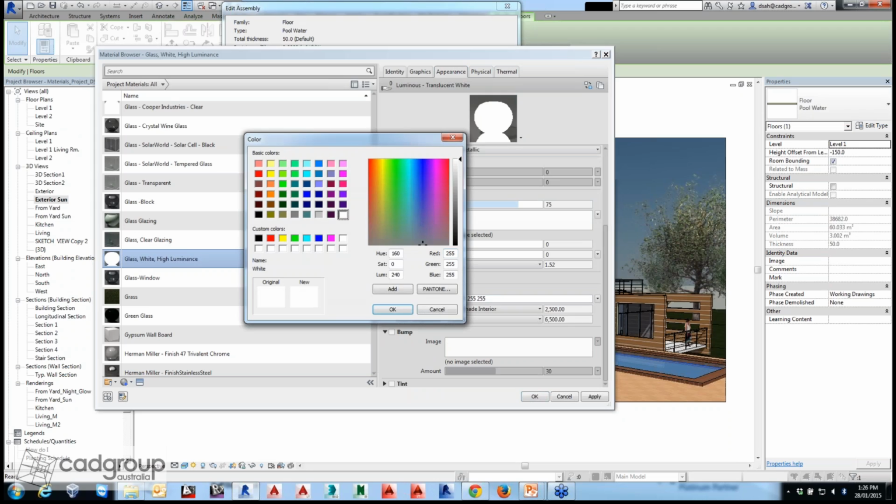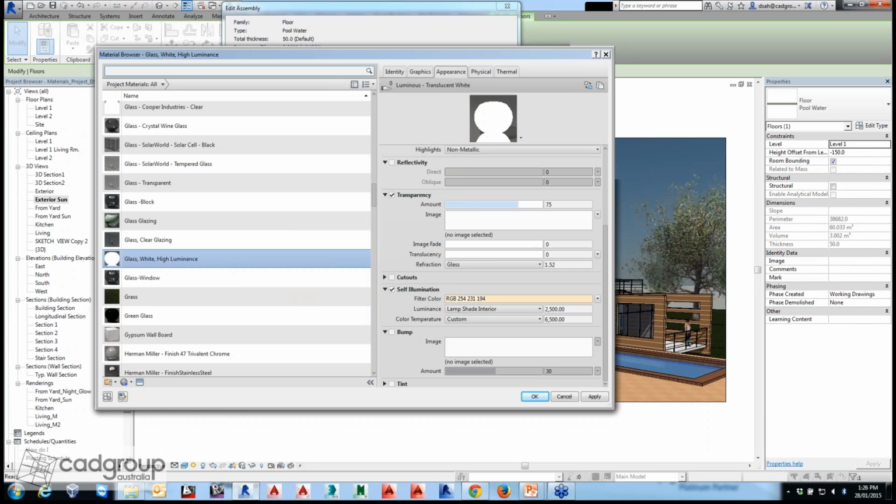So, in fact, if it is a different light source, so it has a bit of color, filter color or something, you can start changing that. So, if it is a little bit of halogen lights, you might want to change a little bit of light filters, and you can say the luminance value. Now, we got a preset of values here, whether you can say to use for the different purposes of the self-illumination. So if you got a LED panel or LED screen, we can see there are a couple of different presets with different values.